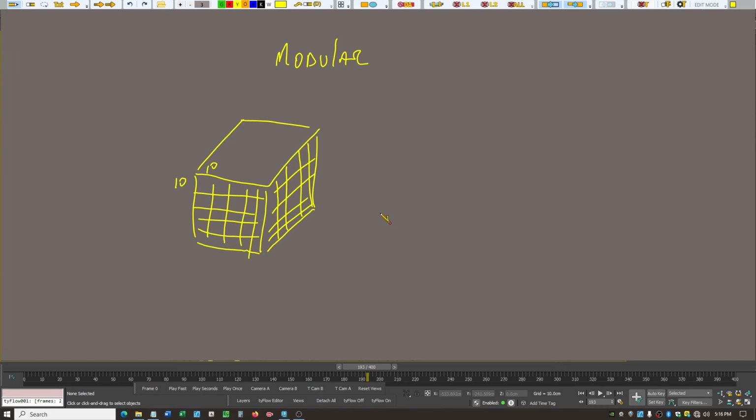Now, when we do stuff like splines and we say that this is going to be a track drop kind of thing, and we're going to use Bezier curves and all that kind of thing, the goal here is to have each end of the track being vertical, right, so that when we connect two tracks together they line up perfectly. In other words, we can't have this on the end so that when we have two tracks they don't line up and the marble's going to fall in the hole here. So regardless of how we design a track section, we need to make sure we spend some time making sure these are perfectly vertical for aligning.